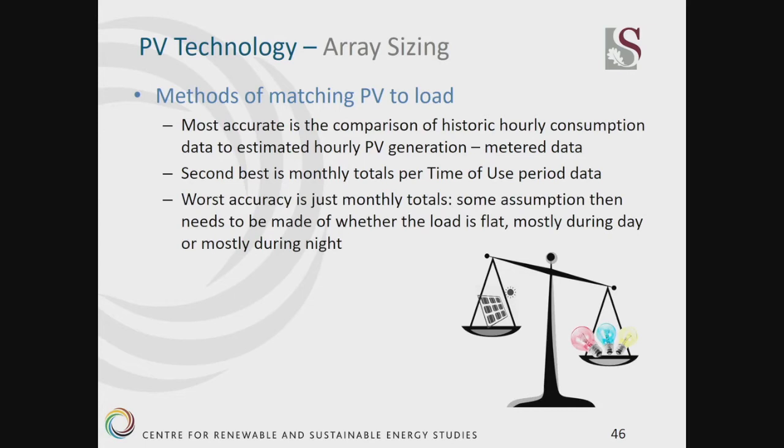So this is typically what you would have at your house in a residential area. It's just the monthly total. What you need to do if you only have monthly total is really consider what load you have running, and also do a proper estimation on when these loads will be running the most to see how much PV you should be installing.